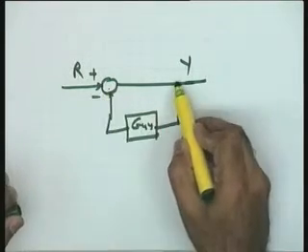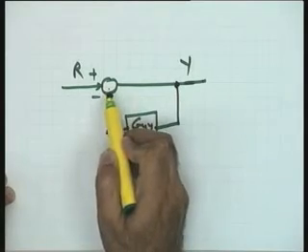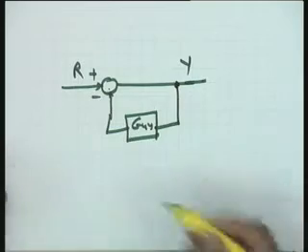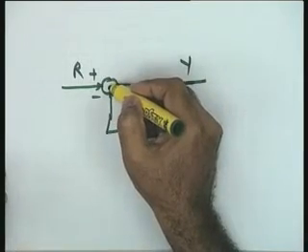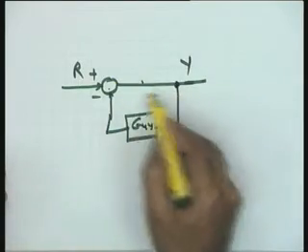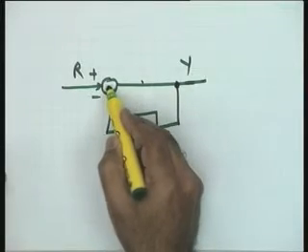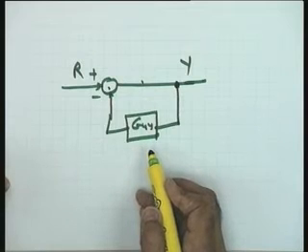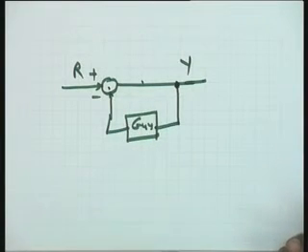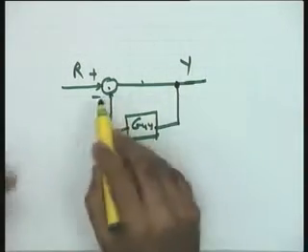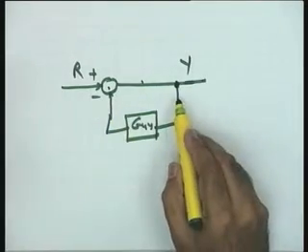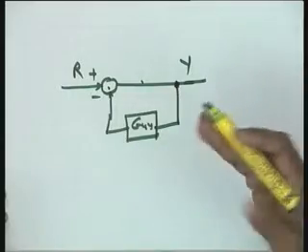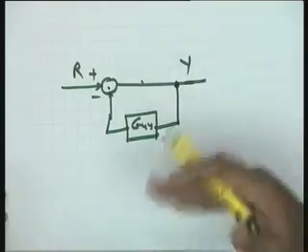You see that this particular signal Y, if it is fed back through G44, you are going to get the loop. You give me the equivalent node for this, the equivalent node for this, if it is 1, because the transmittance at this point is 1, this point and this point is the same, in that particular case this is realizing the self loop. You give me the equivalent signal flow graph. Well, whether in a system we require these things or not, whether we will require a feedback of this signal or not, this will become evident when we come to the physical control situations.